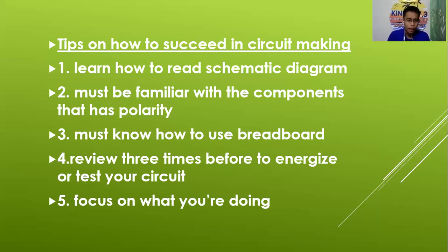Okay, number 4. Review 3 times before to energize or test your circuit. You need to review 3 times, 3 times or more. Tama ba ang circuit? Tama ba ang connection ko? Tama ba yung mga may polarity? Tama ba yung distribution ng pin? Tama ba ito yung pagkakakonect ko? So check, review, and check. Hindi yung test lang ng test. I-review. If possible, gumamit ng tester, gamitan ng tester.